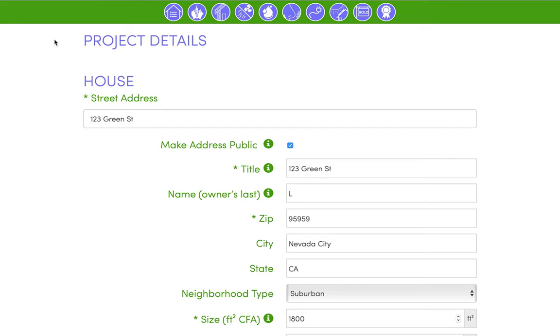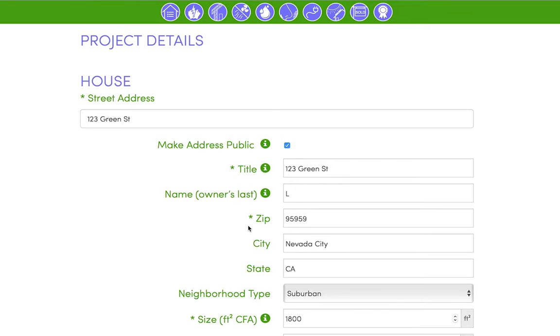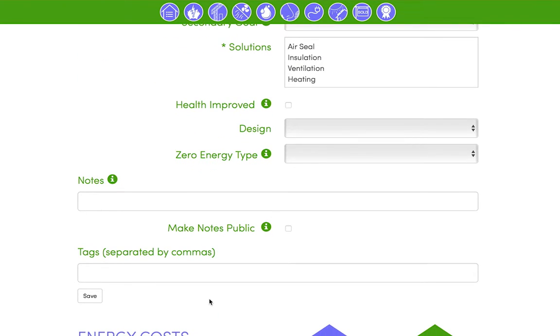Begin a work scope record in the first section, Details. Here, you'll find a few fields that are required, marked with green asterisks. You'll need to have each of these required fields filled out in order to save a work scope record. There is no autosave in AJO. To save your data, tap the Save button at the lower left corner of each section. You'll find a box for text notes at the bottom of each section too.